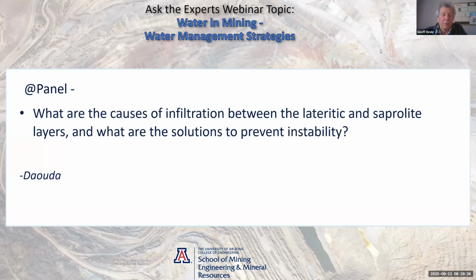That's often heavily fractured, and so many dewatering systems out there have relatively low yield wells into the fractured material below the saprolite. The saprolite is a weathering product, and it tends to be relatively low density, with a permeability typically of about 10 to the -5. It retains relic structure, so it usually drains down.